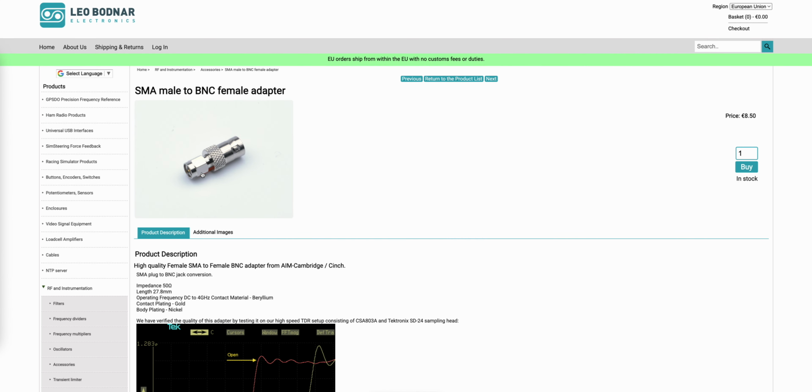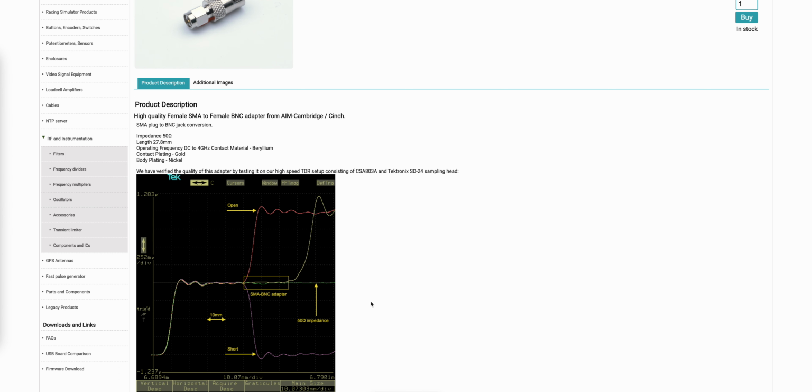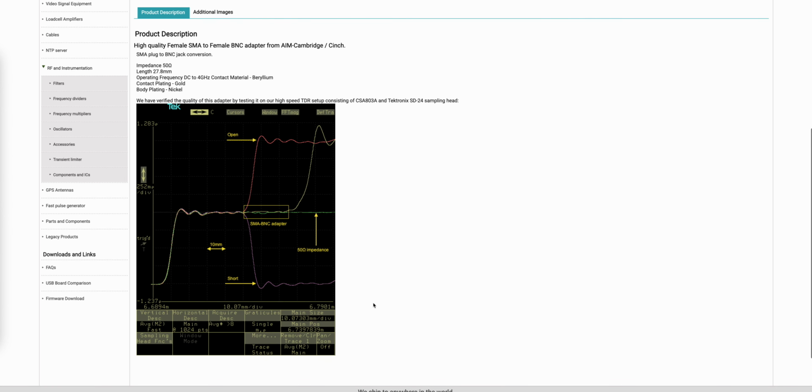This is a very simple case where you have just a connector, but in many cases you can have connector, cables, and you want to see at high frequencies the response of those components. An interesting thing to notice that you may not see at the beginning is that the unit at the bottom is a distance, physical distance. So we're very used to seeing those graphs and we don't pay attention, but in the case of TDR, this axis is distance, which I find very interesting.